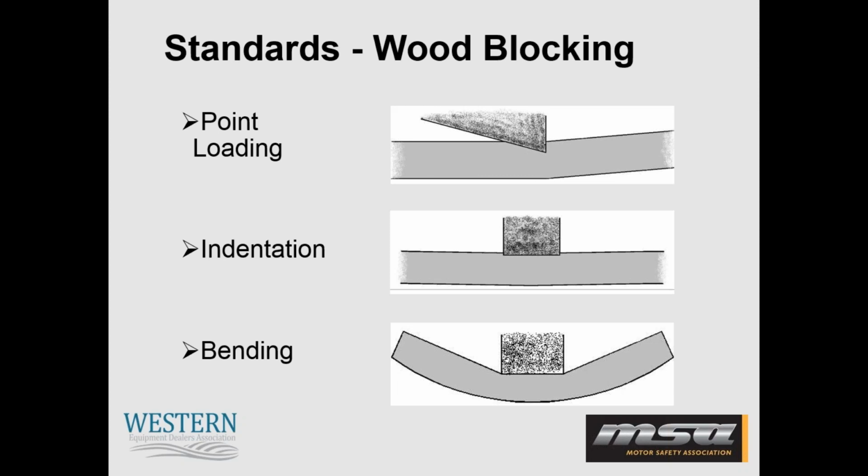If your wood blocking has been super saturated and it's been sitting out in the rain or moist conditions, when you apply a load to that block, it's going to crush and squeeze out the water, much like a sponge, and your block is going to compress. The flip side of that is if you have extra dry wood blocking, it's going to crush very little.